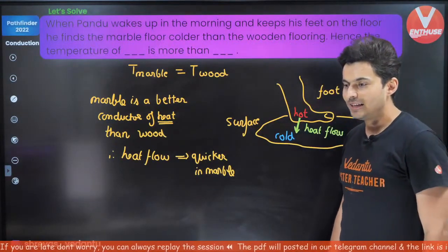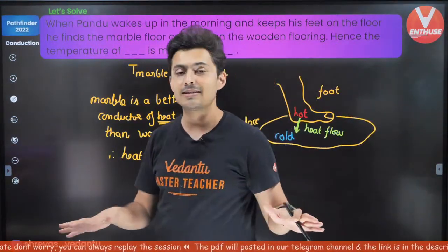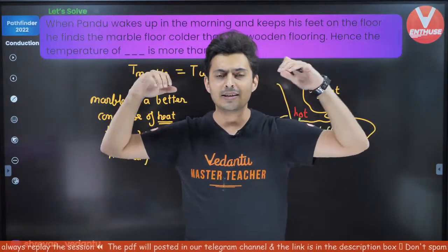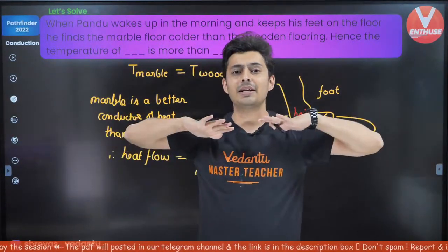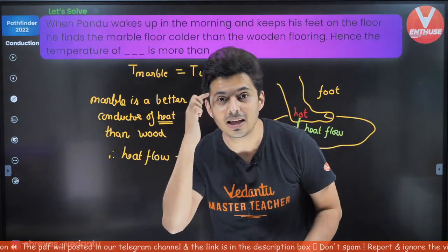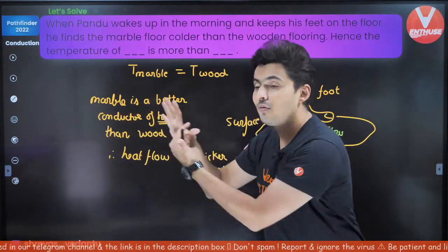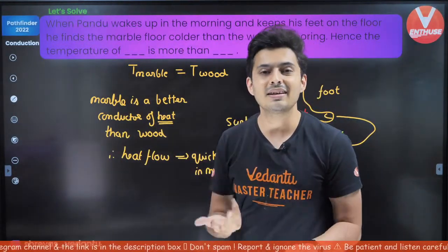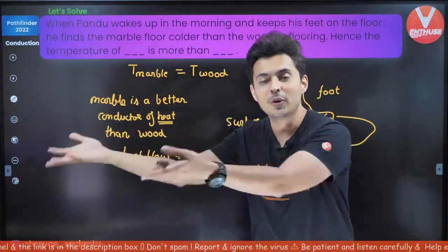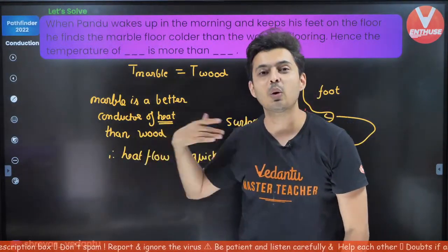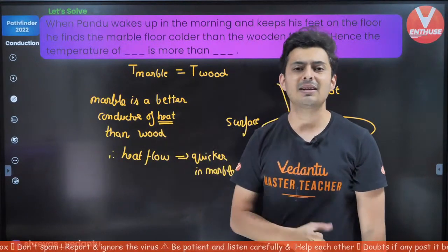Yep. Even in winter season, see, the wood, the marble, the stone, the cement, everything is at the same temperature. But you perceive the temperature differently. Because when you touch something, when do you perceive temperature? Okay, think. How will you sense temperature? Only when the heat flows, right? In or out of the body. If the heat doesn't flow very quickly, how will you perceive the temperature then?